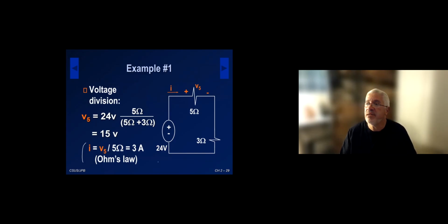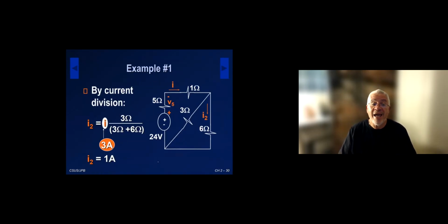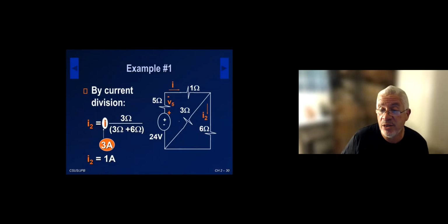These methods are limited. They're not full methods. So we usually combine resistors, and then we use voltage division or current division to get some current or voltage across elements, and Ohm's law as well. So now that I have I, I go back to the circuit, the original circuit. Of course, not quite the original because the 6 ohm is combined here. The original circuit had a 2 ohm and a 4 ohm, but I can use current division right here to go from I to I2.